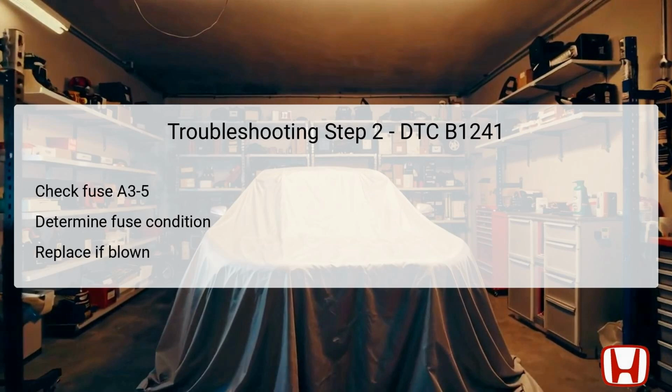However, if it is blown, replace it and retest the circuit. It's crucial to address any recurrence of blown fuses, as this indicates a possible short or other serious electrical issues that need immediate attention in the corresponding fuse circuit.